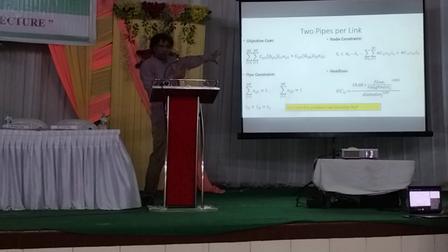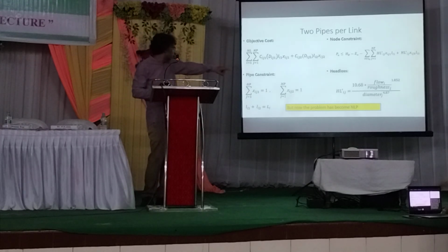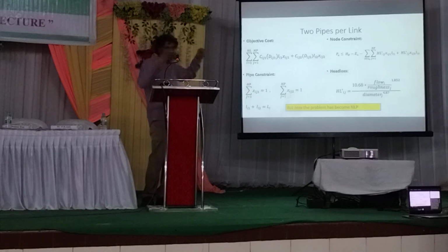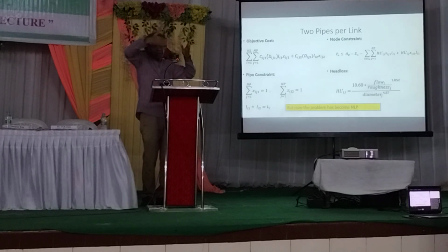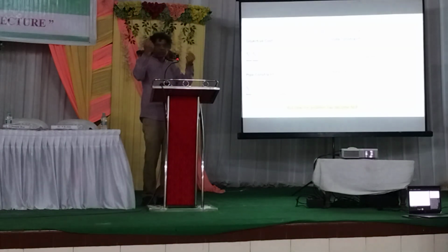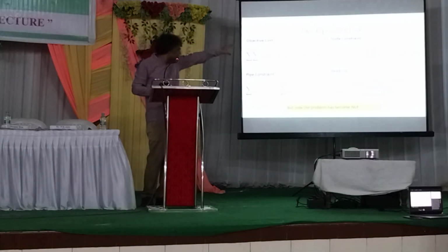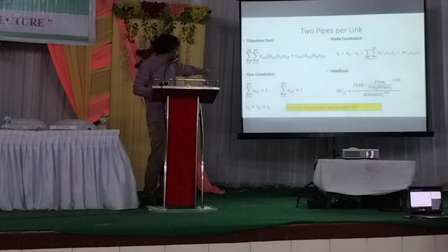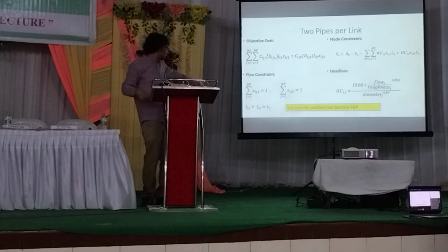It's a very similar formulation for those who are mathematically inclined. I can share this slide later on. Basically, now in each link, say here to the nearest water tank, you can have at most 2 types of pipe. So X1 and X2 each represent which pipe diameter has been selected. The rest is the same thing. There is a pressure loss along the path, and the 2 lengths together should make up the length of the pipe. That's the constraint. Next.